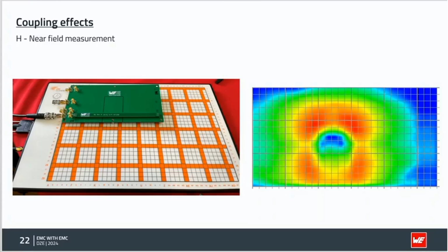It only measures the really near field. And by that you can see the outcome of the magnetic field that's going to be generated due to the cutout. The circuit board itself is quite simple. It's the easiest version you could create. The bottom side, the big one, is a complete full ground plane. Well, not completely, because we have that cutout. And on the top, connected with pin headers and socket headers, we have a transmission line. Also one circuit board with full copper.